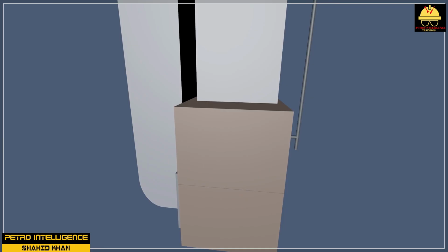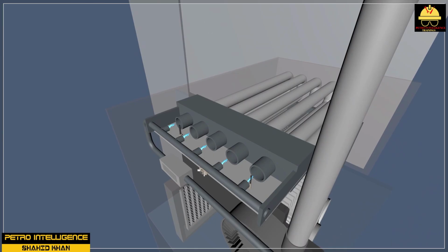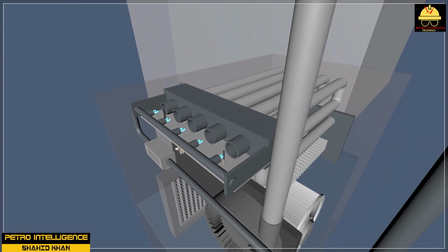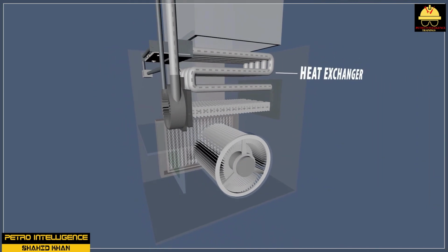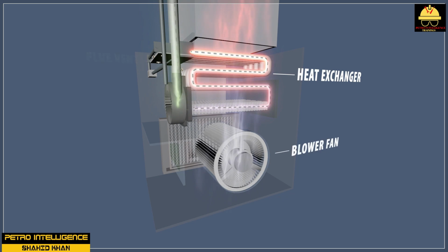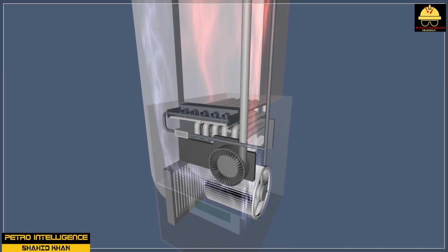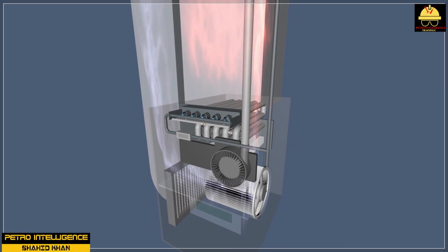Furnace applications and theory of operation. A furnace, that is, a fired heater, is a device used to heat up chemicals or chemical mixtures. Fired heaters transfer heat generated by the combustion of natural gas, ethane, propane, or fuel oil. Furnaces consist essentially of a battery of pipes or tubes that pass through a firebox. These tubes run along the inside walls and roof of a furnace.